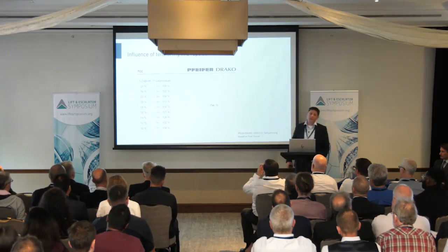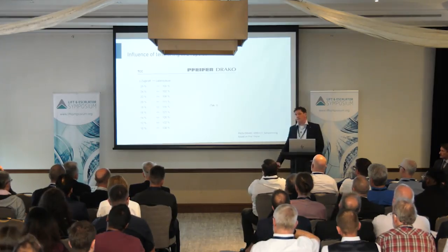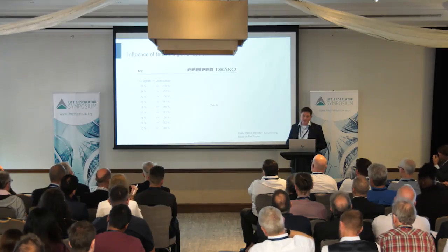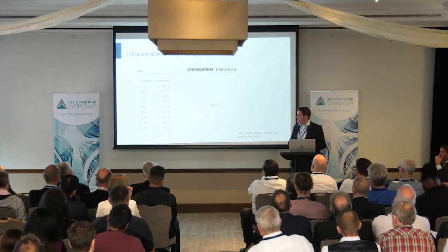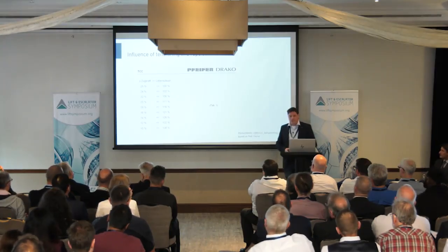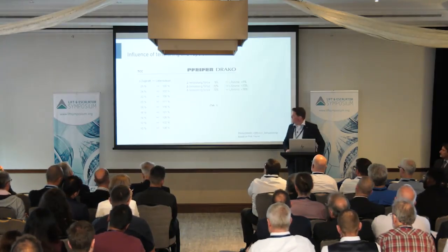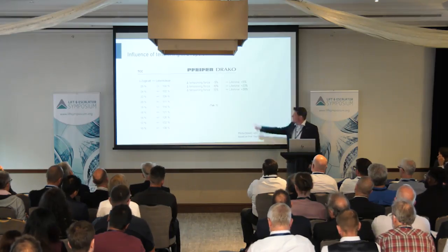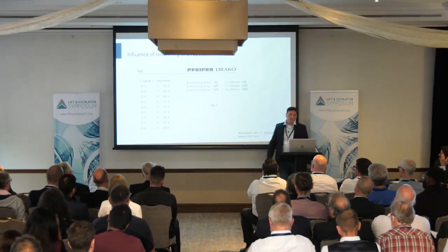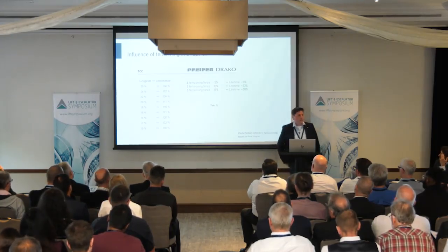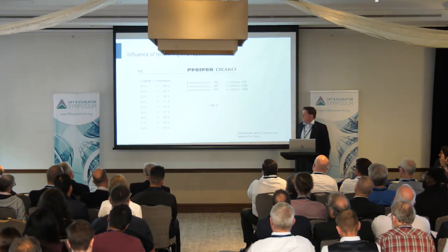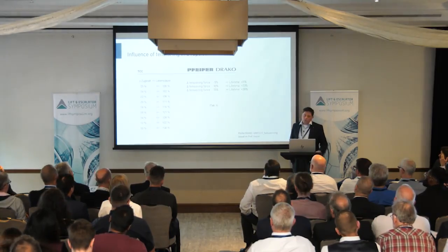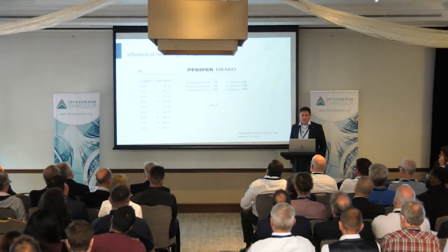Feyrer, when he wrote this formula, expected that a well-maintained lift has ropes which deviate by roughly 25% of the carried load, and defined that as 100% of rope lifetime. So look what is happening. If you decrease the deviation between the ropes just by 5%, the rope lifetime, according to this formula, is increasing by roughly 11%. Decreasing the deviation by 15% already gives almost 40% more rope lifetime.